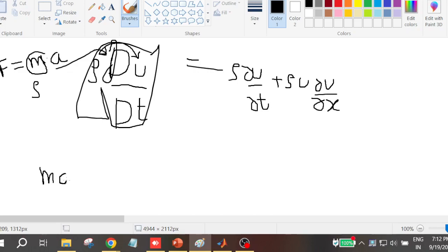Now the mass itself can be written as rho into v, and acceleration as dou u by dou t. There is no change with respect to compressible or incompressible here. And since we are taking volumetric, this v will also go. What remains on the left hand side is nothing but rho into dou u by dou t, which is the same for compressible or incompressible.